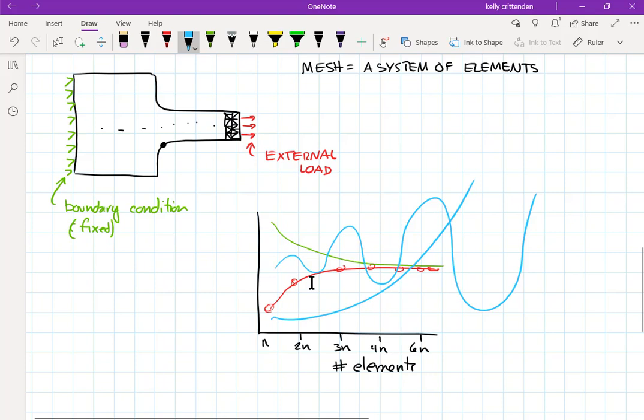When we actually build this model in SolidWorks, you can watch it deform. It'll exaggerate the deformation, and you can look at it, and after a while of doing this type of thing, you'll know if that looks right or not. So if it's deforming the way you expect the real piece would deform. And so there's a lot of, don't just run as many elements as you can and take this data point because it may or may not be good.